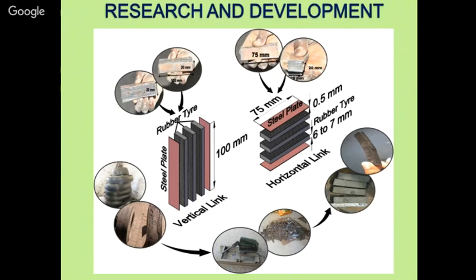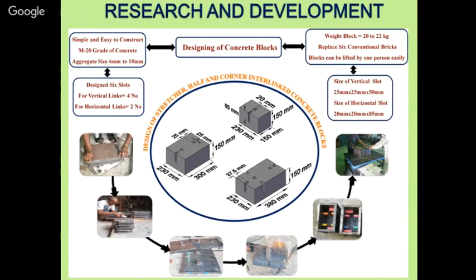And in these concrete blocks, as you have seen, we have designed the grooves in such a way that the groove size should not be more than 5% of the total mass of the block. If it exceeds that limit, the strength of the concrete block will be less, and in earthquake force, this viscoelastic link will break our concrete block. We don't want our concrete block to be disturbed or damaged. That's why we designed the grooves in the concrete block very smartly.